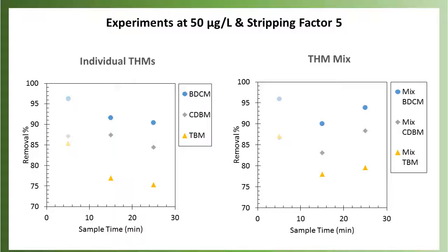They don't last. Bob Rasko has done some work with these. I've asked Bob for a report on them. We've tried to talk with Liquicell. We love the idea, we'd love to use these. But until Liquicell moves away from using the polypropylene support and goes to PVDF, these are basically a non-starter. They're that troublesome. They cost so much to replace that we were getting ready to put a whole bunch of these systems in.